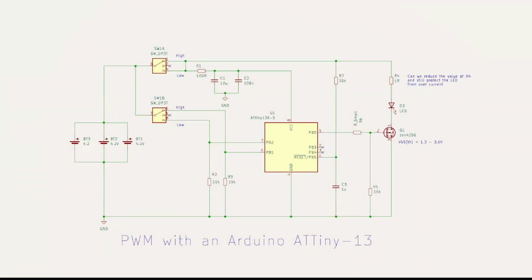So I started to have a look at a more hardware and firmware solution using an Arduino, or in this case an ATtiny13, because it's an 8-pin chip, and it has all that we need. It has digital inputs for the monitoring of the power state required, and a PWM output that's quite easy to drive. And this gives us the ability to configure the PWM signal to provide the two brightness levels, and we can decide on how much current we want and things like that. And we could add extra functions like flashing to warn of a low battery voltage, etc. And so it's quite flexible.